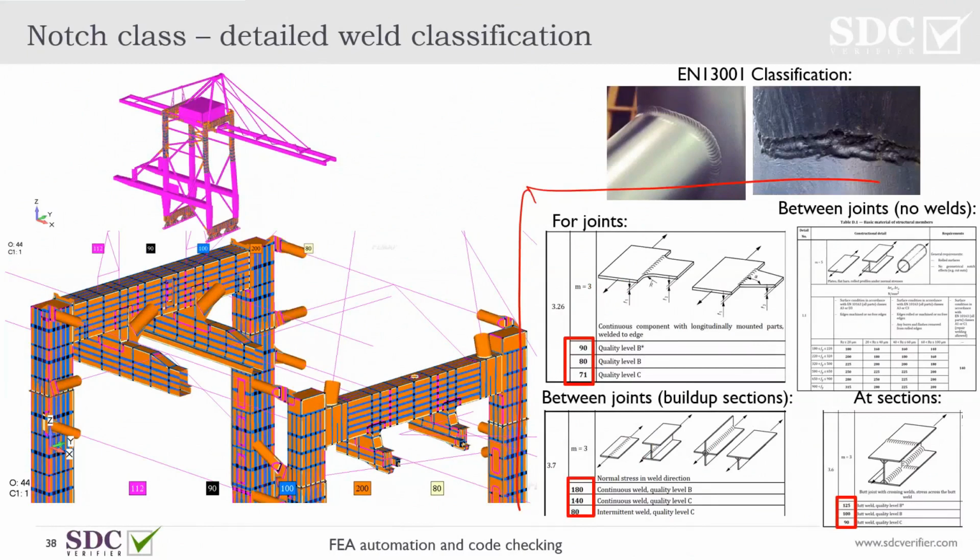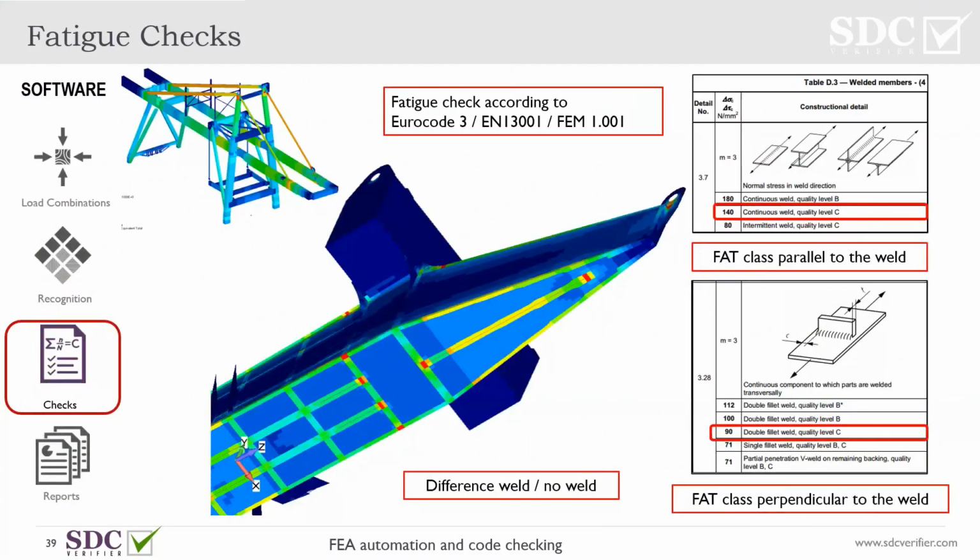The results accuracy is also amazing. At the end, what you get is, of course, that the fatigue damage for the non-welded part is less, so most likely it's within the limit, while all the welds show higher fatigue damage. Especially at the weld intersection locations, we have locally high fatigue damage, which we should deal with somehow. That's why, by the way, you have all these red holes in a typical girder: if you have a cross section of it, you have an internal section here, and all these holes are made to avoid crossing welds, especially because of fatigue.